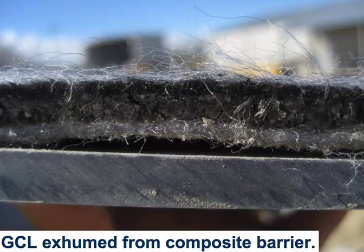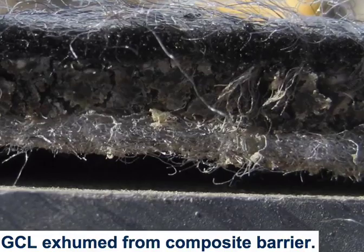So depending on if this is a calcium bentonite or a sodium bentonite, if it's a sodium bentonite and it's permeated with something dilute, it'll swell and still have a low hydraulic conductivity. If it's a calcium bentonite, even if it's permeated with something dilute, it won't attain that low hydraulic conductivity.